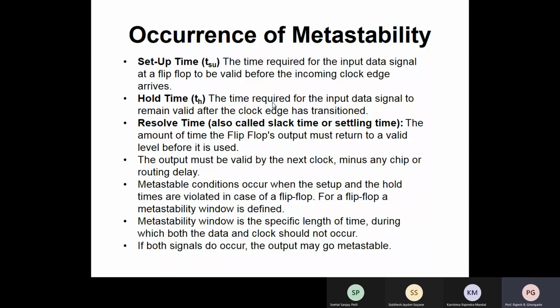What is the hold time? Hold time is the time required for the input data signal to remain valid after the clock edge has transitioned. We'll see this with the figure so we can understand properly. Then we have something called resolve time, also called slack time or settling time. This is the amount of time the flip-flop's output must return to a valid level before it is used. Output must be valid by the next clock minus any chip or routing delay. Metastable conditions will occur when timings like setup and hold times are violated in a flip-flop.